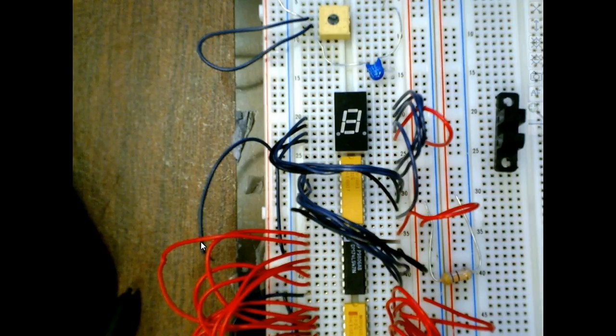Why do you know that? Because it's low active and I'm putting a high on there. Am I doing a ripple blanking input? Yes or no? Why? Because it's high and it's low active. Am I doing a ripple blanking BI input? No, because it's high. So that means I'm putting a high into this thing. I'm putting all highs, right?